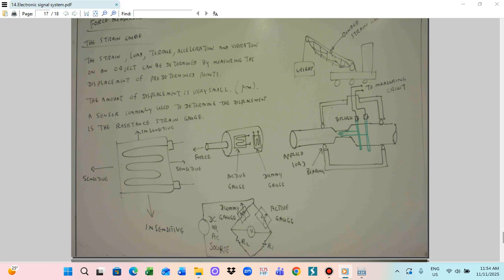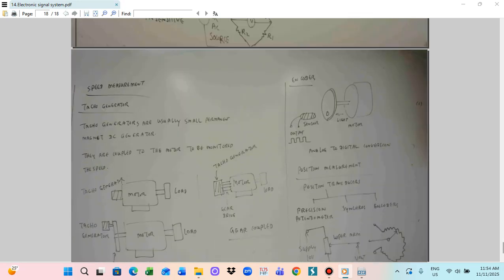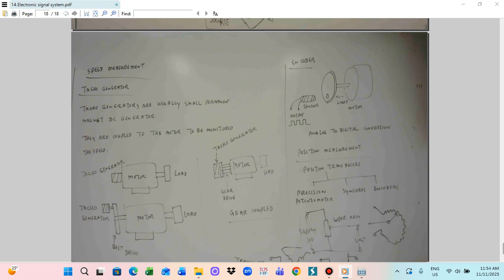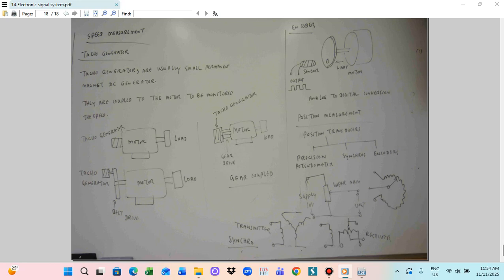When I worked on a ship, what happens is that on one side we run the generator. The diesel engine is driving the generator. So these two generators need to be synchronized. One side, the engineers make a mistake. When they put these two generators in synchronizing, if one machine's phase is 180 degrees off, at that time one machine can be driven as a motor. So one machine becomes a motor and makes a back running, so that all the diesel generator, all the pressure bars, everything comes out. They broke it. This is a very important aspect.